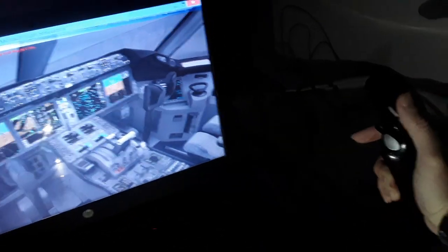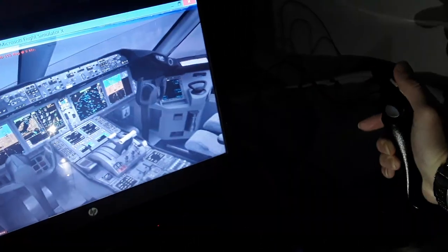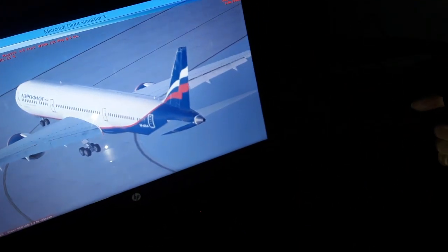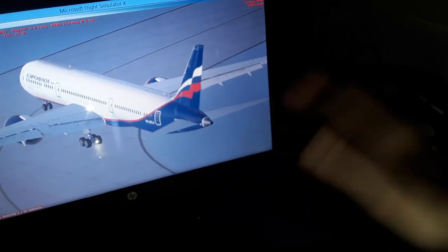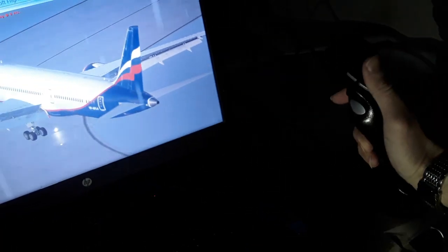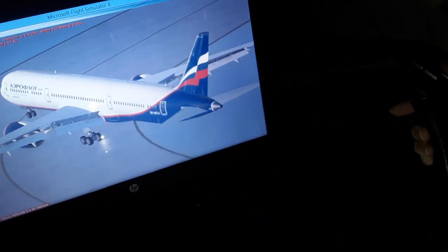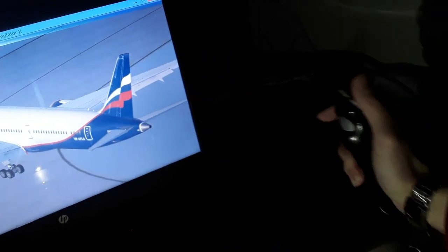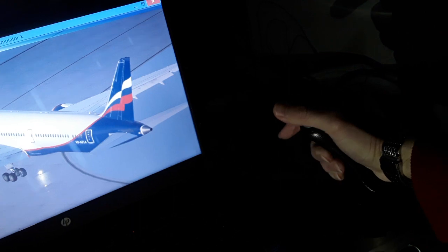So same function, side stick or control wheel, also climb and descent. You can move all together, full flight controls. So side stick is the roll axis, left and right, or a control wheel in the Boeing. You have also full flight controls together, all axes of controls, using the elevator and rudder together.